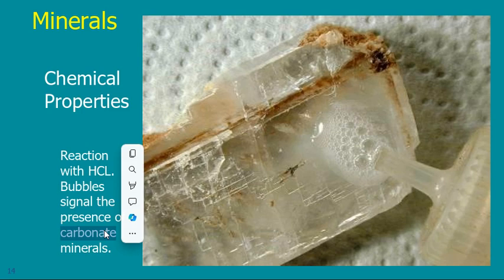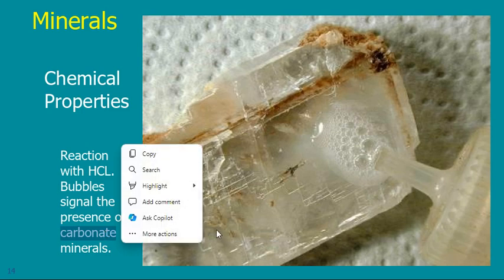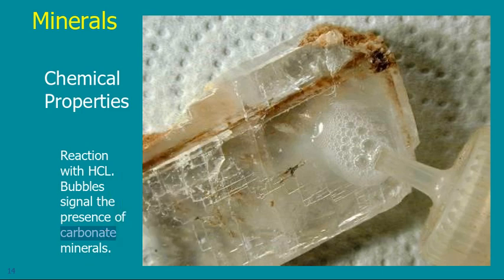So if I put my building on top of a material that includes carbonates, it means with time the volume of it will diminish. So if the volume diminishes, my building will fall. So I need to check if this material contains carbonates or not.